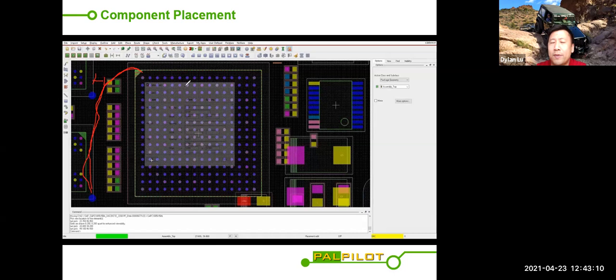So when a computer is doing the routing and the auto router kicks in, it will say there's not enough space. What would it do? It will start putting in a via, which is a hole. So this trace will go down to another layer to route. Okay. So you say, oh, that's an easy solution. We just add layers. Each time you add a layer, when you go to fabrication, it's a cost. Okay. And your signal integrity by going down there and then coming back up is never gonna be as good as if you go on the same surface.